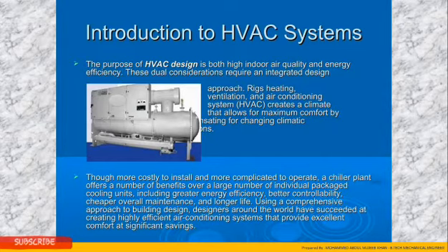Though more costly to install and more complicated to operate, a chiller offers a number of benefits over a large number of individual package cooling units, including greater energy efficiency, better controllability, cheaper overall maintenance, and longer life. By using a comprehensive approach to the design, designers around the world have succeeded at creating highly efficient air systems that provide excellent comfort at significant savings.